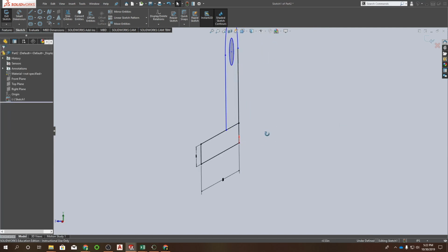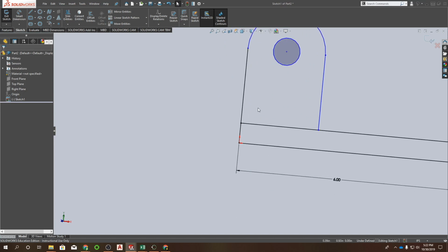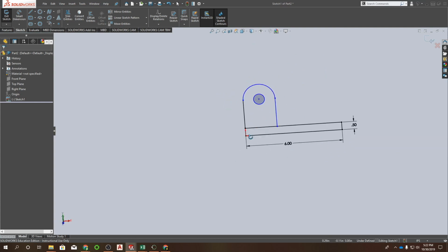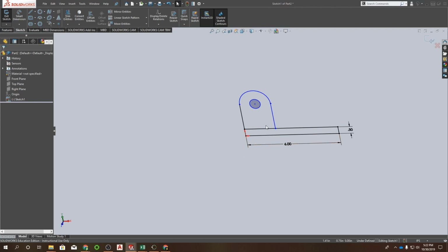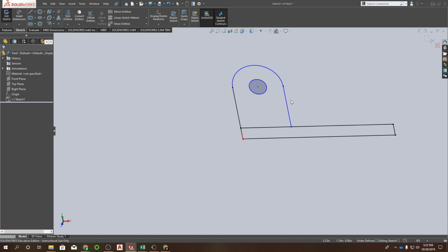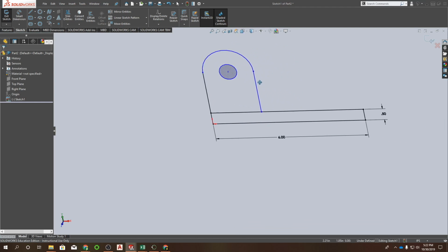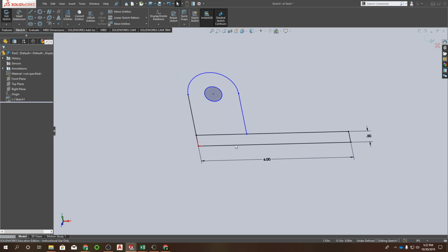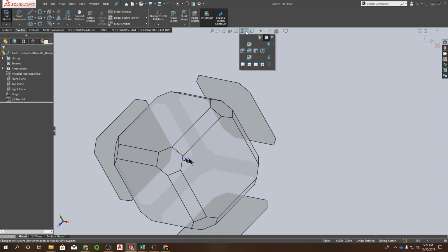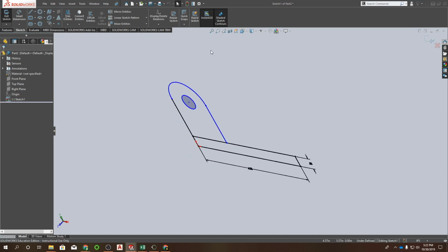Now that's attached there. Oh, I just held down the middle mouse button. That rotated, which you'll probably do because that's pan in AutoCAD. If you hold down, let's think here. Hold down Shift, that's a zoom in, zoom out like that. If you hold down Control and hold the mouse button, that's pan. If you want to get your view back to looking straight at what you're sketching, you can come up here, click here. This big cube thing pops up, but you can come down to here. There's all the different views you want. So I can do front there, or as you can see, Control 1. So I'm going to do Control 1.